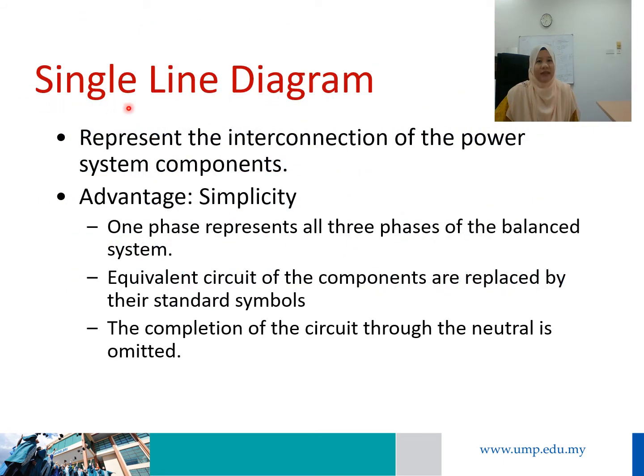Okay, we start with single line diagram. So single line diagram represents the interconnection of power system components. Based from its name, the single line diagram actually uses a single line to represent all three phases of the balanced system. So the equivalent circuit of the components can be replaced by their standard symbols, and the completion of the circuit through the neutral is omitted.